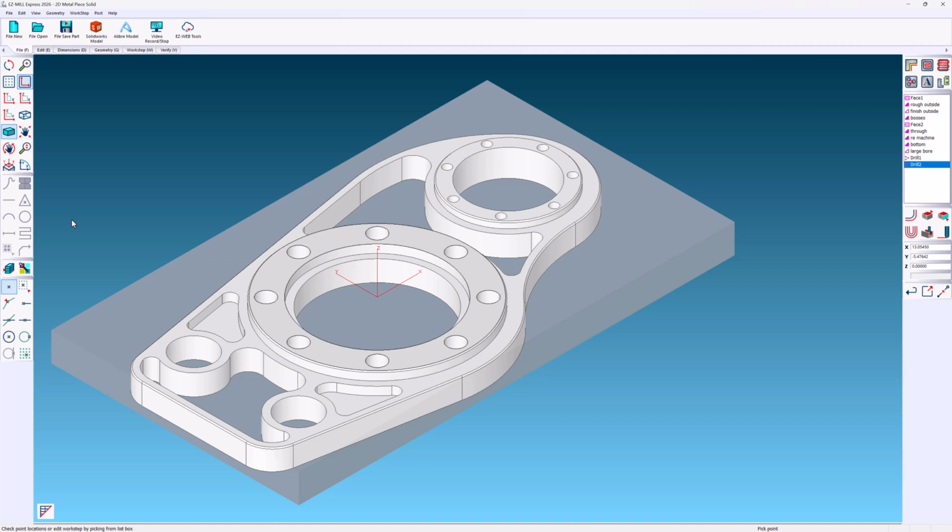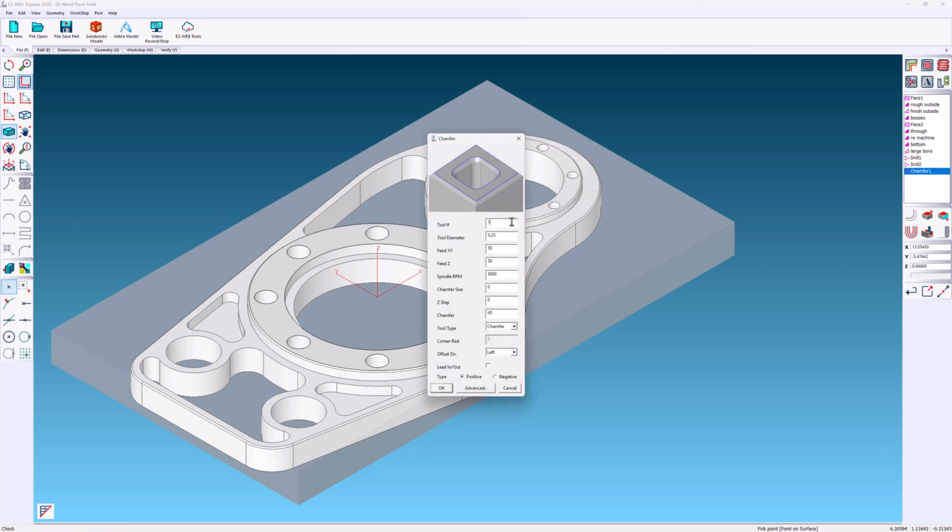On this model, we have 3 chamfers to machine. You can skip the chamfer size and angle. EasyCam has you covered and supplies the values based on the selected faces. There are many ways to machine a chamfer. The tool options include chamfer, flat, ball, and bull. With any tool, you can feed from the top to bottom in smaller increments along the tapered angle. Just add a Z-step.